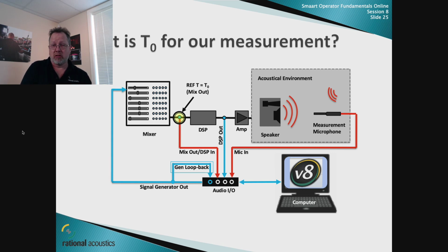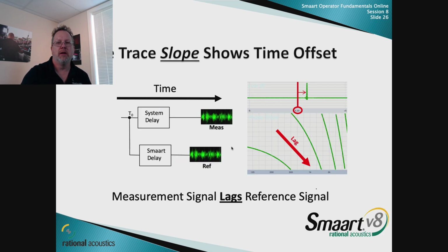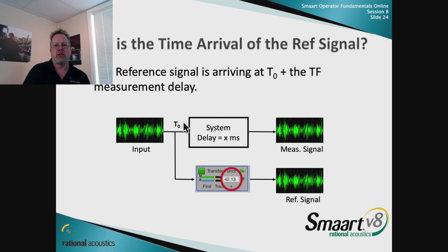And basically through this DSP unit, there's 4 milliseconds of delay. When we first measured it, there were 4 milliseconds of delay through that unit. And so what I had done was that I quickly had measured it and set 4 milliseconds of delay, so I had basically delayed this signal to this one. So that's what we did right here, right? I grabbed it at time 0, I measured the delay, I applied that delay, and so they were in time with each other.